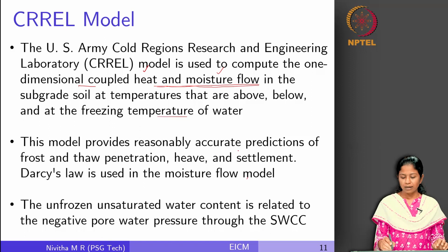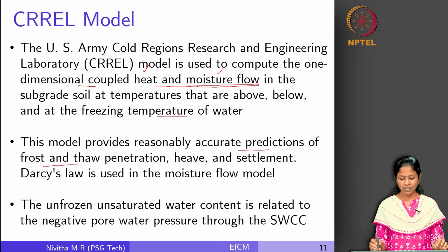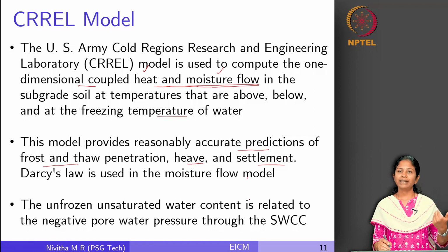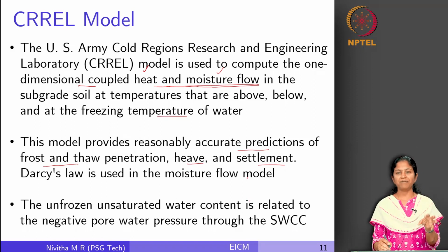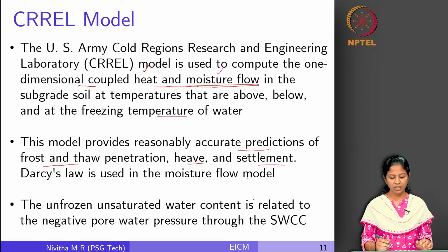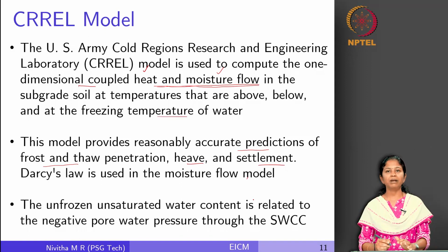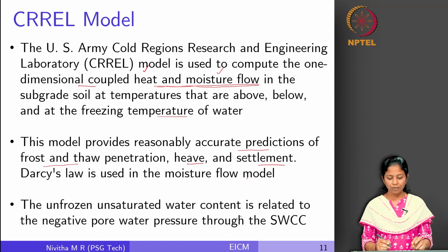It provides reasonably accurate predictions of frost and thaw penetration, heave and settlement in the pavement. So, it predicts the entire effect on the pavement. It calculates the heat and moisture at a certain depth, what the frost and thaw penetration is for a given moisture content and temperature combination, what the heave effect is because of this, and what the settlement is because of all these phenomena, right.